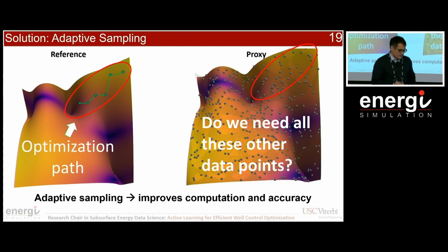So with that, what you can do is adaptive sampling. Instead of front-loading your computation and generating a lot of data at the beginning, you can start with very few samples where you are in the iterations, and then do your local prediction during optimization. And every few iterations, you can add more samples. Sometimes you have to actually remove samples because those samples may not be helping you anymore, right? That's where the terminology active learning and adaptive sampling comes from, because sampling is done based on the use case and the application and the algorithm that you're using.